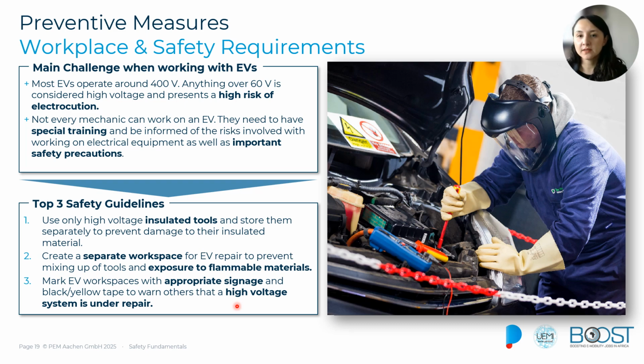And all of this means, for instance, using these black and yellow tapes that are used to designate different areas, for instance, to designate the high voltage system areas and where we do repairs, and also to have some visual and auditory alerts of when there is a potential hazard, and how to keep people at a safe distance from the different work that we may be performing.